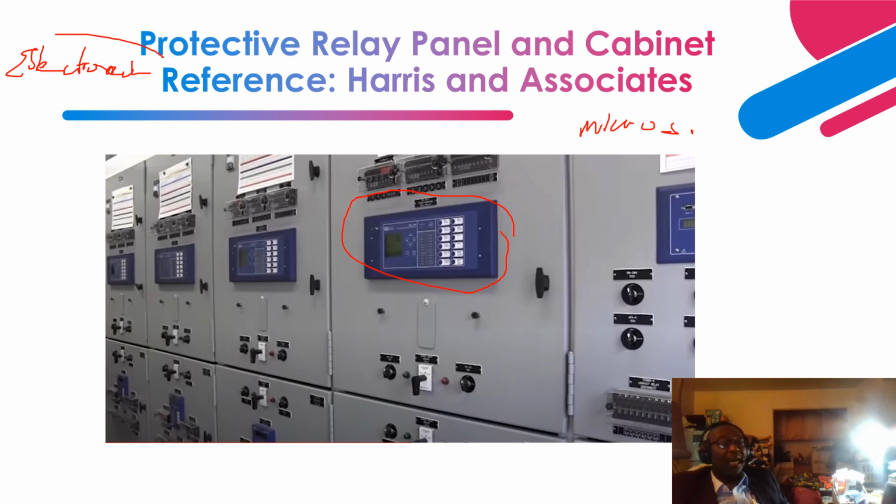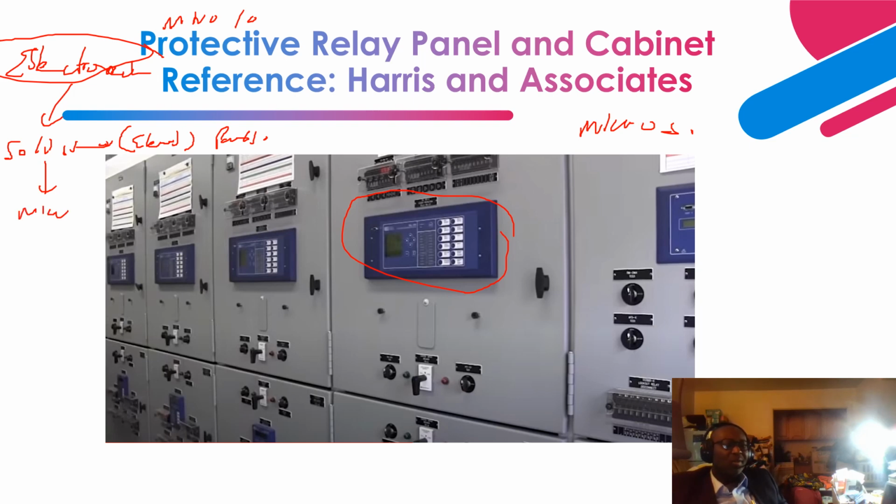So during outages, during minor and major outages, they are planned so that the relays are removed, bench tested, and the settings are adjusted as required. Then from electromechanical relays, it evolved to solid state protective relays, which just have additional elements and utilize power electronics. But now it's microprocessor relays, which have a lot of protective elements that it's utilizing.